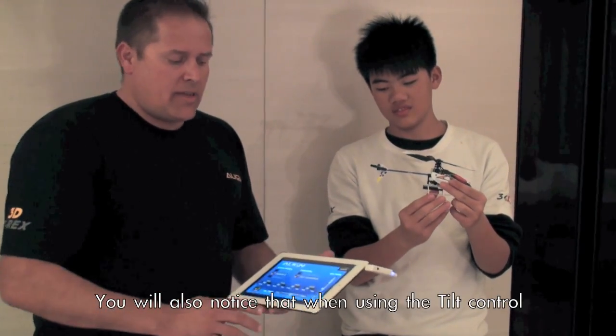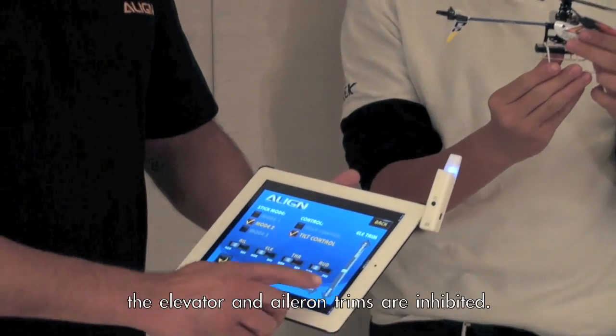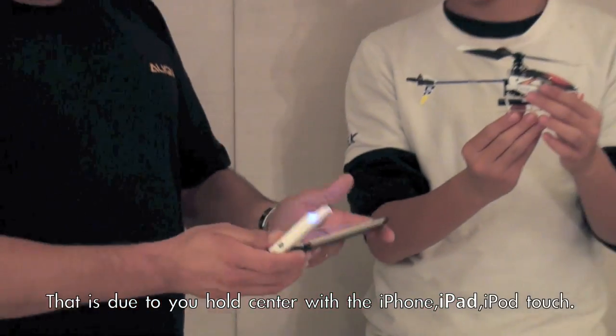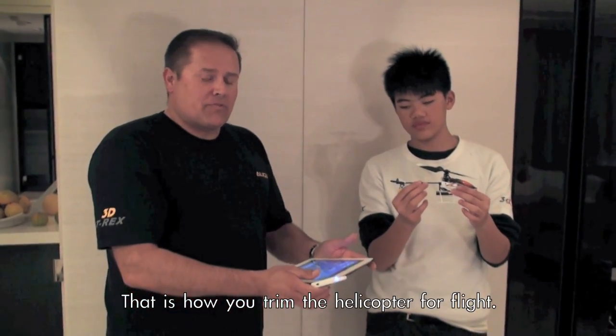You'll also notice that when you're utilizing tilt control, the elevator trim as well as the aileron trim are inhibited. That's due to you actually holding center with the iPad or iPhone. So that's how you trim the helicopter for flight.